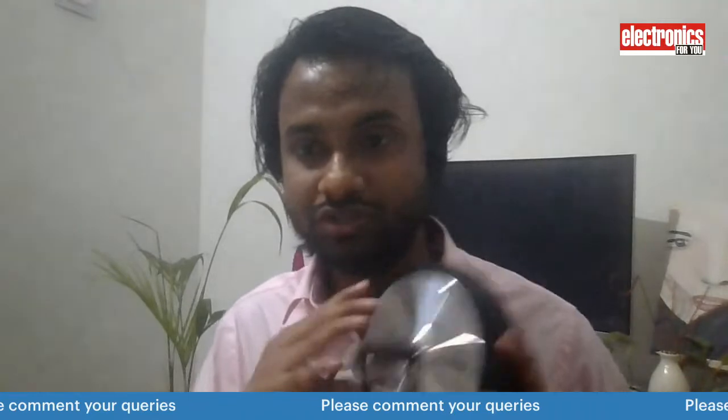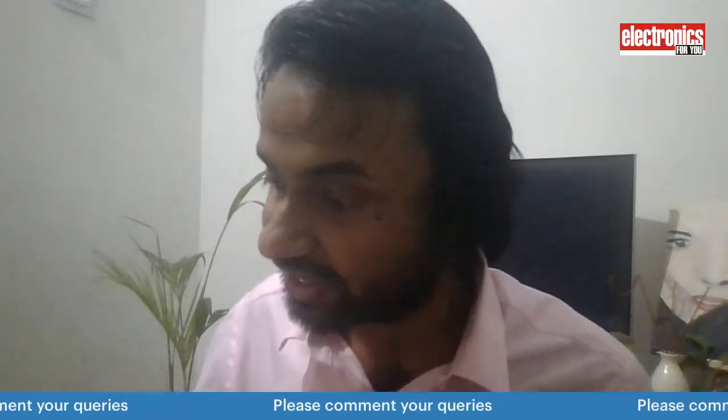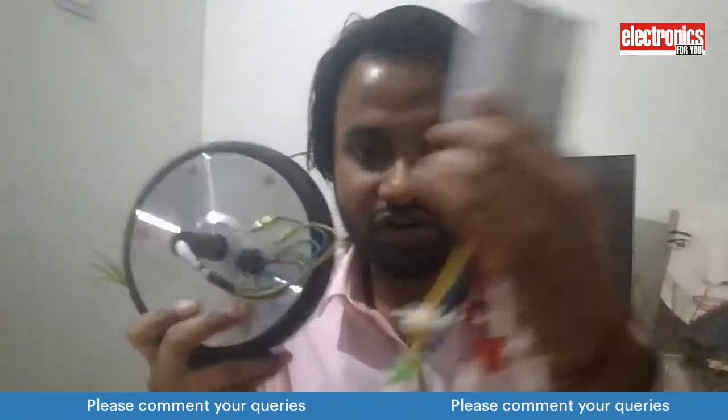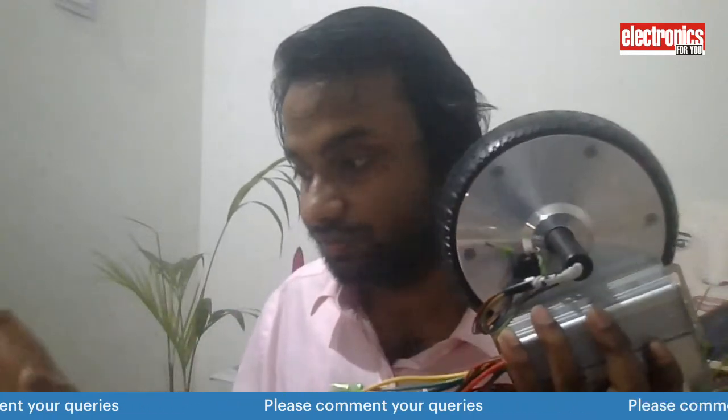This is only the first session. Here we have checked how we can connect the LiDAR and get the data, and how we can make an anti-collision system that will give you the alert. In the next session, we will control this hub motor of the EV with this controller, and then we will make an auto braking system. Whenever the LiDAR detects some vehicle coming so close to it, it will stop this hub motor and do the auto braking.